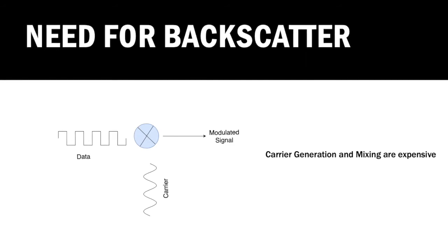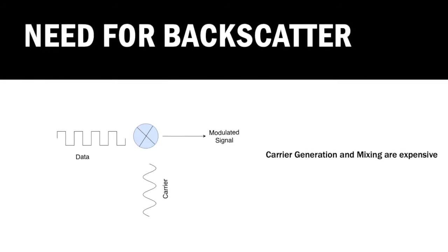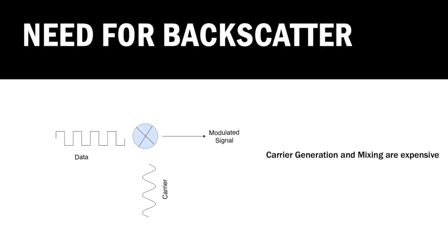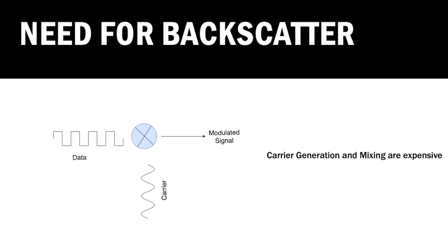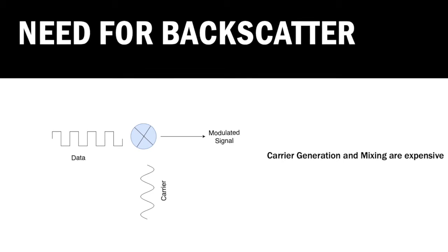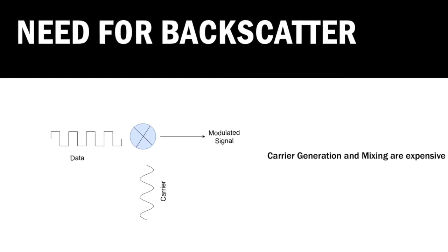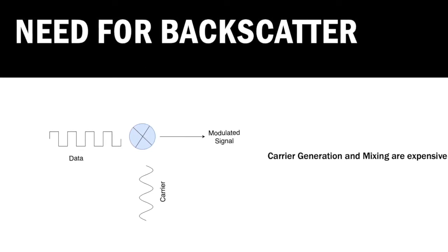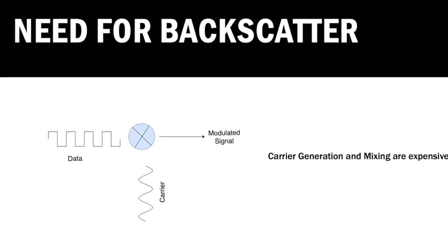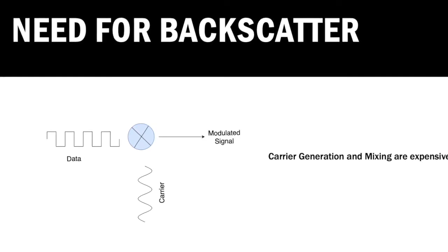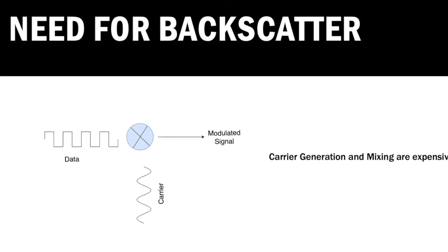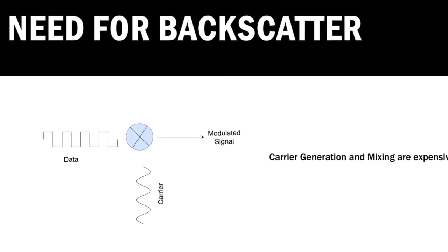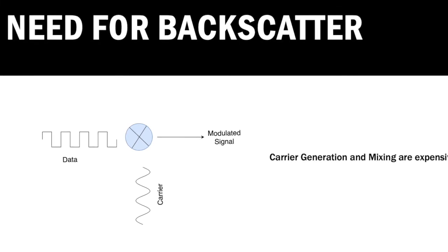However, the local carrier generation as well as mixing are very expensive operations, which means that to have both these operations on the device, we will need a higher amount of energy for doing packet transmissions, and it makes it hard to squeeze the energy requirement of these devices such that we can design devices using local carrier generation and mixing without battery reliably.